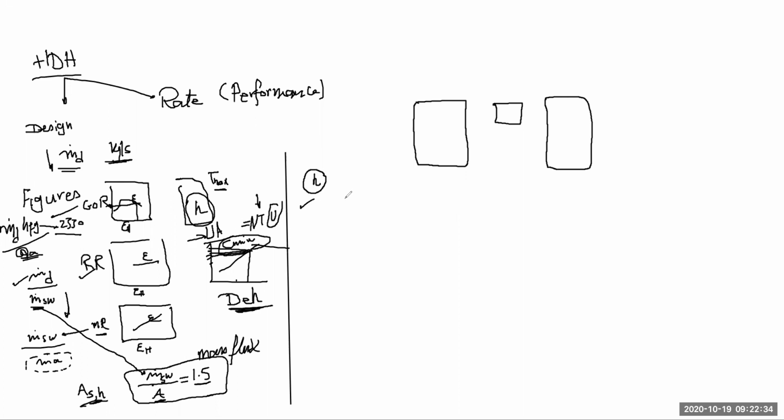What you would be expected to do is to run the energy balance and mass balance, of course, for the system. The only mass balance that we would have, now I'm talking about a water heated system, is that m dot water coming to the humidifier is going to be m dot brine plus vapor, which will be carried by the air. So the mass balance is that m dot water entering will be m dot brine rejected plus m dot evaporated.